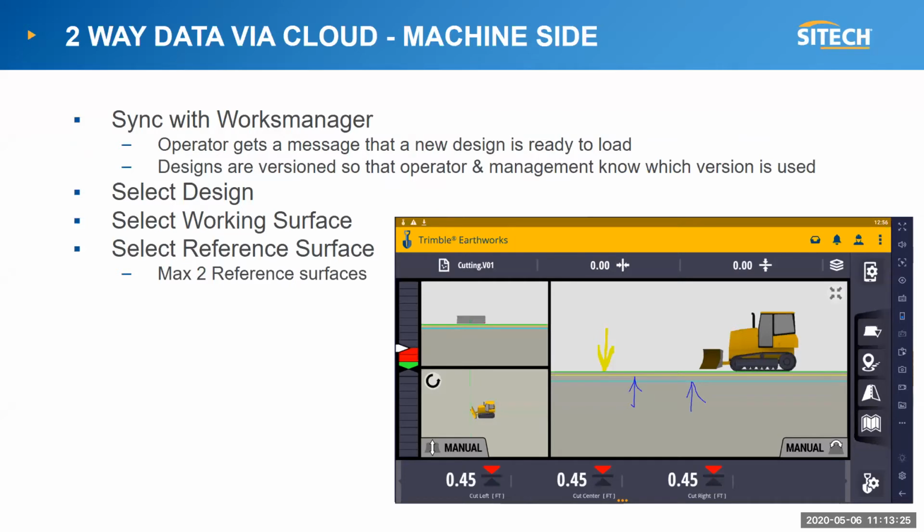You will also get your cut fill tolerance lines in here if you want them, colored red and blue for the different tolerances. So the operator can see everything on one screen, in the cross-section view and the profile view, all that he needs to do in there. It's really helpful to see where he is on the designs, and how far he has to dig down till it gets to the next level.